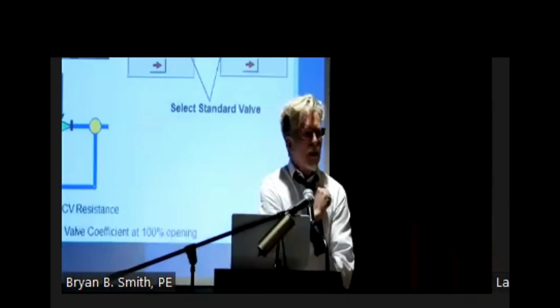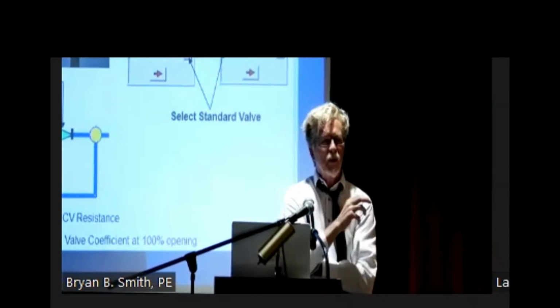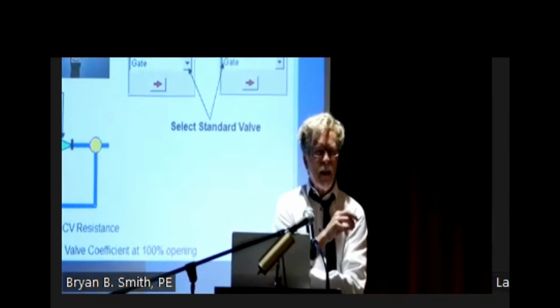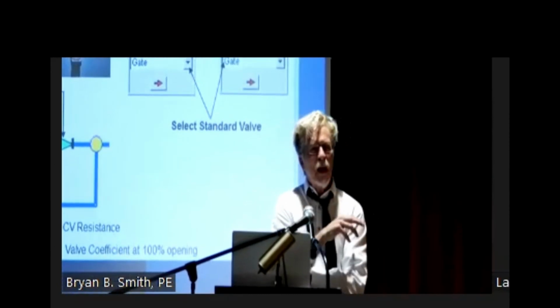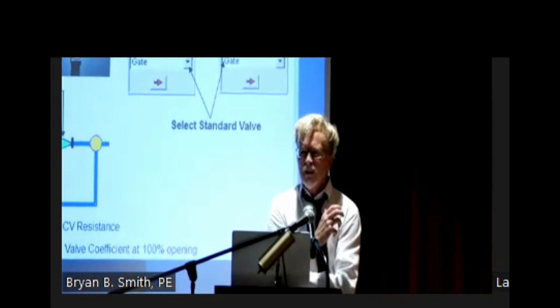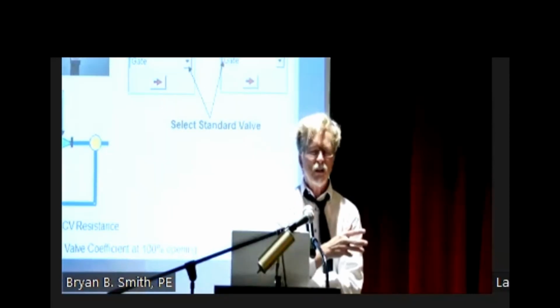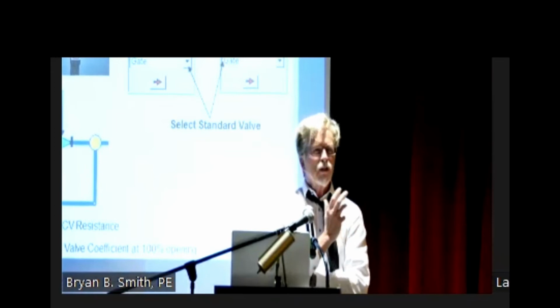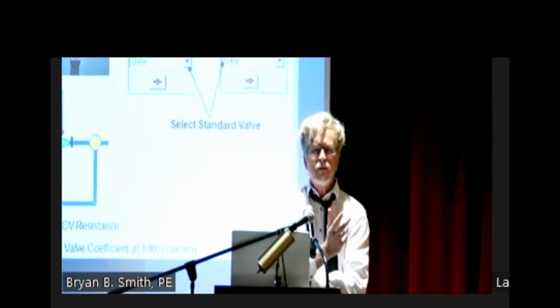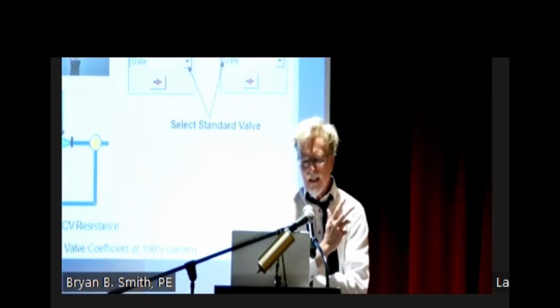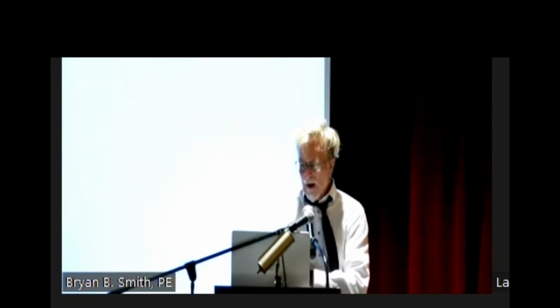So how do you solve that problem? And again, through computer modeling, analyzing, look at that pressure transient, and to solve that problem, you've got to control the change in velocity within the system. So this is where we look at surge vessels, pump cycle control vessels. How do I give and receive energy? How do I accept that energy? And it starts with computer modeling of our system.